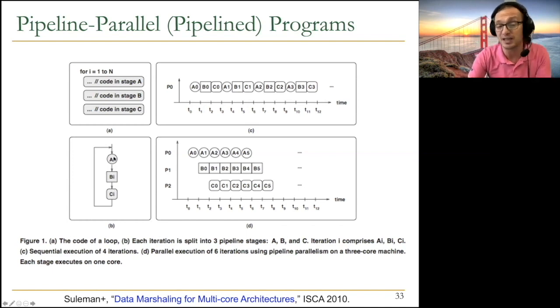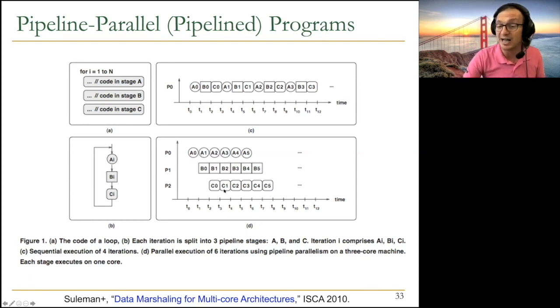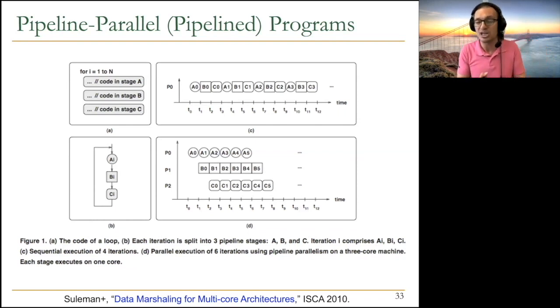And there are multiple other reasons to potentially do this. All of the A's may be operating on similar data, for example. They may have very good data locality, so that you want to keep that data inside this processor. B's may be operating on similar data, such that you want to keep data over there. You basically maximize the locality over here as well. Again, I'm not going to go into that aspect right now, but this is a programming paradigm that has been inspired by systolic computation and stream processing. And this also fits nicely with the systolic array principles.